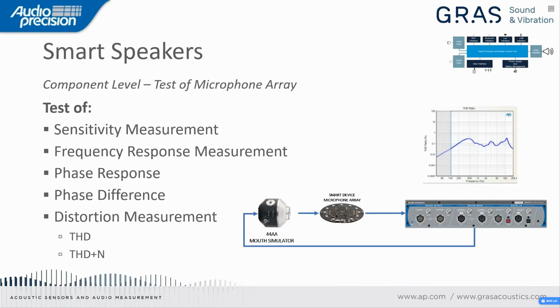Component level test of a microphone array. Yeah, it's very similar to the setup we saw before. And in this way, we are going to measure sensitivity, frequency response, and phase response, because we might have more than one microphone in our microphone array.